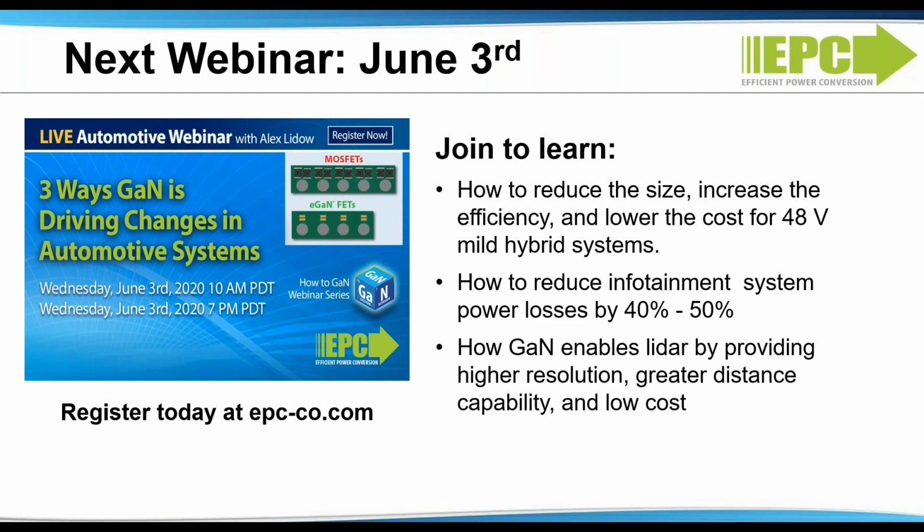What is the failure mode when EOS occurred? Well, EOS is a catch-all. It stands for electrical overstress. I'll refer you back to the phase 11 report. If you do electrical overstress from drain to source, there's one failure mechanism. If you do an electrical overstress from gate to source, there's a different mechanism.